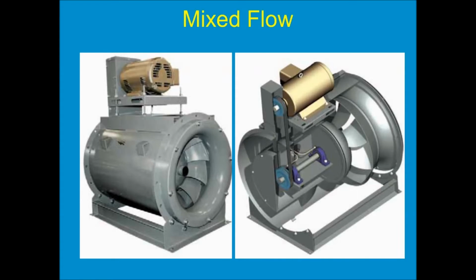So almost in every case, at least every case that I've looked at, whenever we're looking at moving a certain volume of air against a certain amount of pressure in an inline application, when we compare a centrifugal tubular fan to a mixed flow fan, the mixed flow fan can do the performance with a lower RPM, less horsepower, and less noise. So it's just in those inline applications, it's just a better choice. It's a very, very efficient way to move the air.